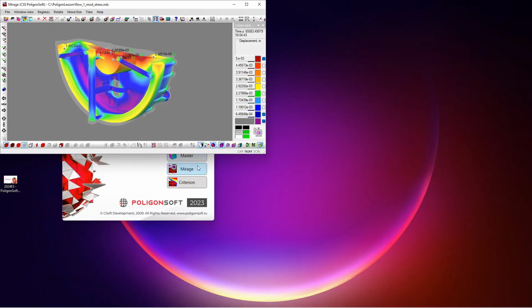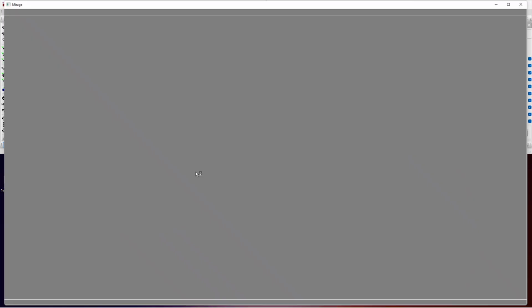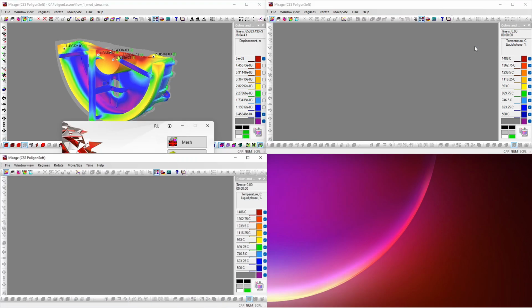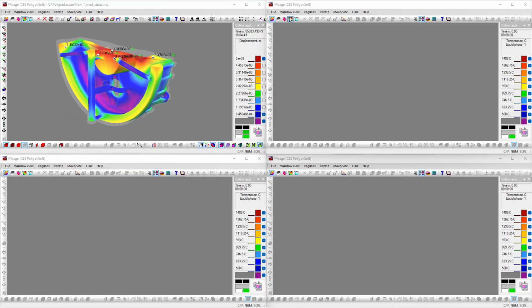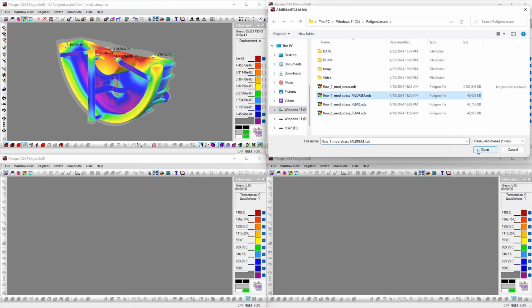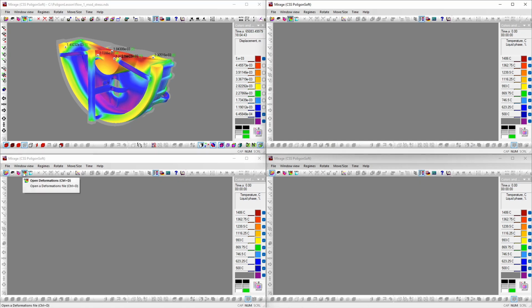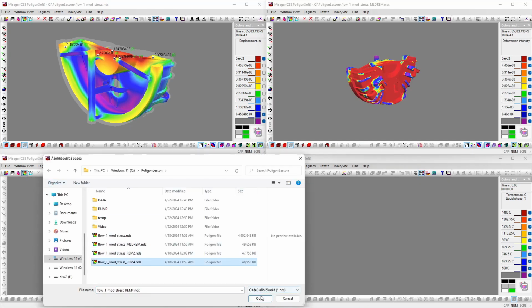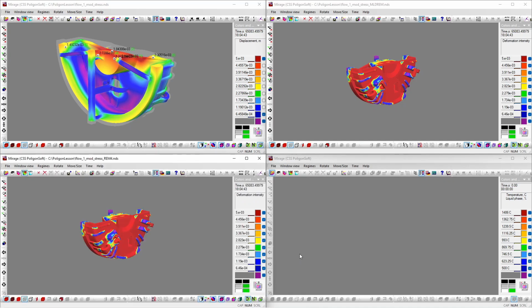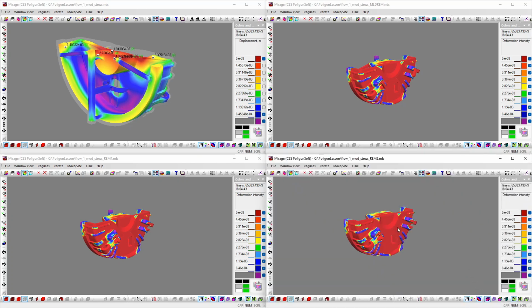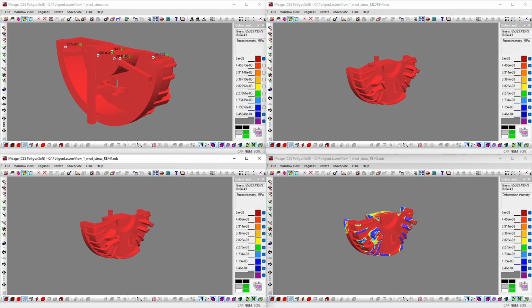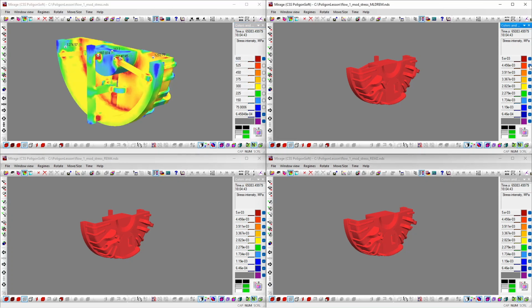Now let's see how the picture changes after mold extraction and removal of the gating system. I will leave this post-processor on and run 3 more copies to see all the states simultaneously. I will open the stresses after mold extraction. We will compare the stresses. Let's set the maximum scale value for all values equal to the tensile strength of our alloy, approximately 600 megapascals.